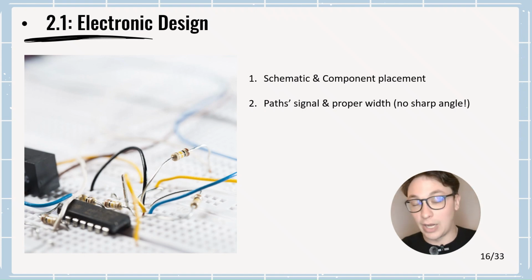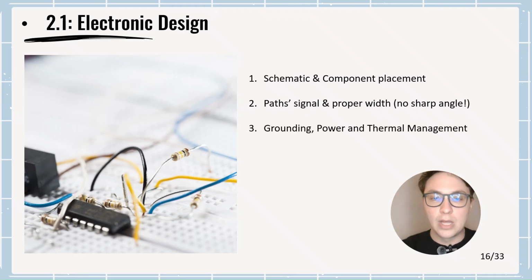They do matter a lot, so it's always better to have larger paths for higher current. Of course, it's always better to not introduce sharp angles, otherwise we're going to create cracks and ruptures. Of course, it's good practice to properly ground and separate the grounding from the power of the PCB, and to think wisely about proper thermal management of the electronics.